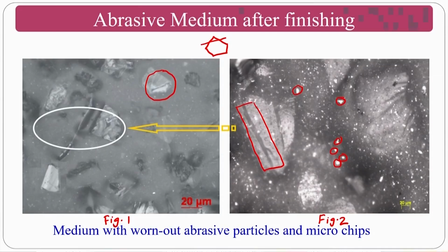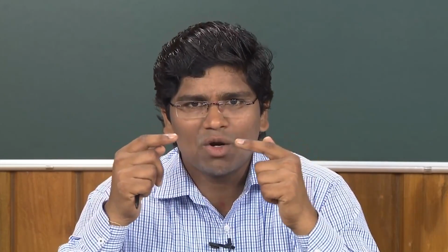That means, the summary of this particular class: we have entered into the advanced abrasive finishing processes, and we took the first and foremost, highly important process, called abrasive flow machining and abrasive flow finishing process. Why is it called the abrasive flow machining process and the abrasive flow finishing process? Since this abrasive flow finishing process uses a semi-solid to liquid type of cutting tool, it is mostly used for those internal holes where intersections and burrs are there.